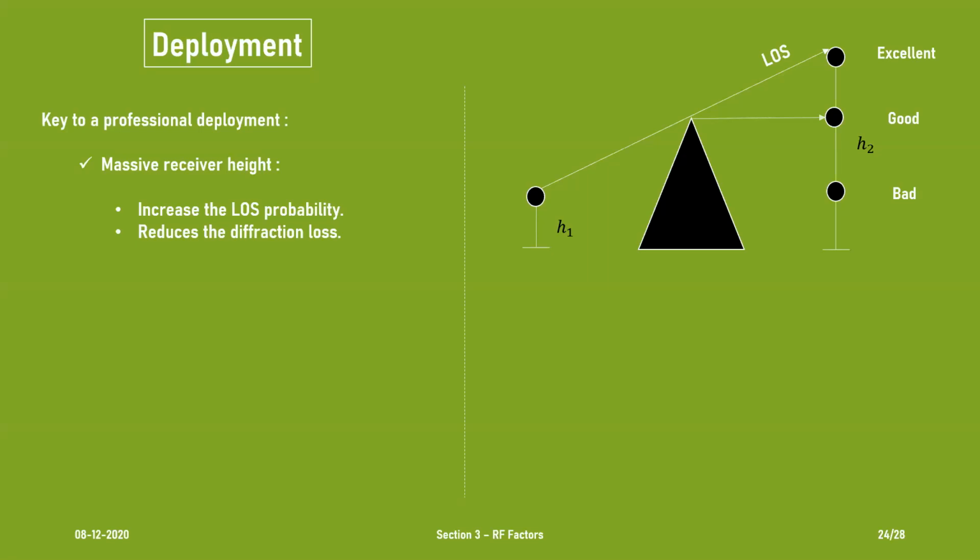If you're having a manhole monitoring sensor, then you have to have an enclosure. You have to dig it inside, 1 foot below the ground. That is something that you cannot change. It's only specific to the use case that you're working on. So you're fixed with the transmitter height depending upon the use case, but the variable is the gateway height, and that is up to the network operators.